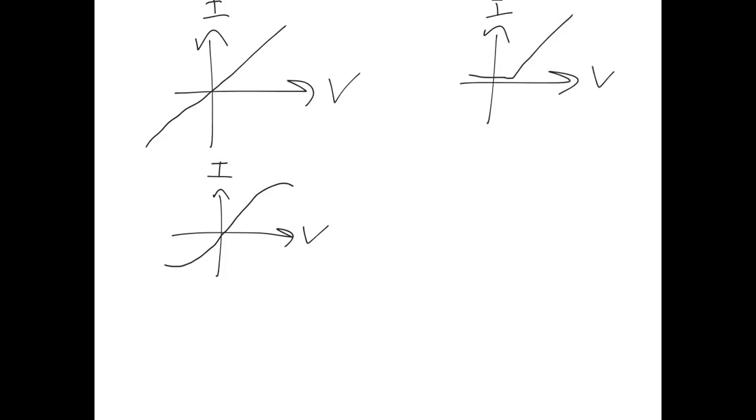And what that tells you from the filament bulb's point of view is what I was trying to explain earlier, which is that the resistance of the metal filament increases as its temperature increases. This is because the ions in the metal filament vibrate more as the temperature increases, so they resist the passage of the electrons through the filament more.